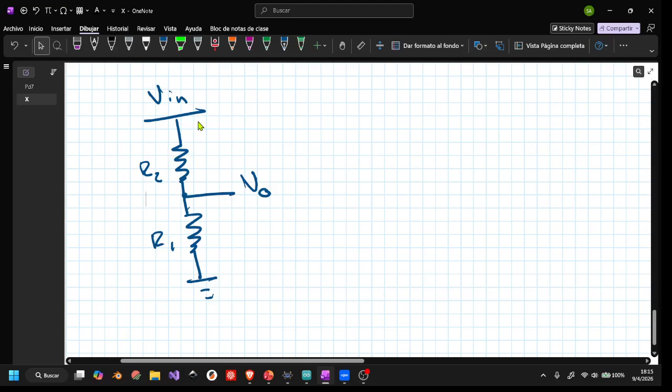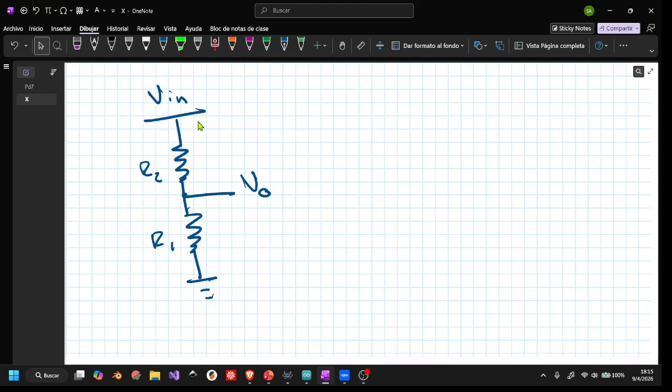That's a voltage divider. If you connect two resistors in series, you can generate a fraction of whatever voltage you have there, right? So for example, if I have as an input voltage 5 volts, I can generate here whatever voltage value between 0 and 5 volts, right? Okay. We can also connect here a negative value. Right now it's not important, right? Anyone remembers the formula for a voltage divider?